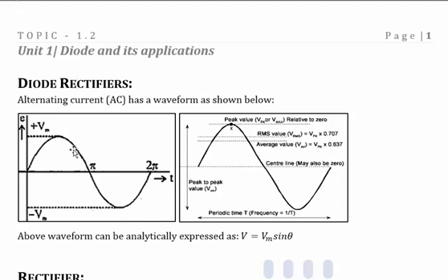So the device which works on DC will not work on such type of AC signal. So we need to convert this AC into DC for that device to work normally, because when we give such type of signal to a DC device like mobile or any device that works on DC, that will damage it, because this positive pulse will try to push current into the device, and this negative pulse will try to fetch the current from the device.